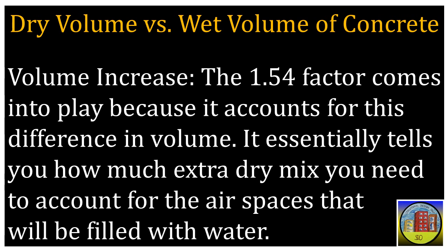Continuation of dry volume versus wet volume of concrete. Volume increase: the 1.54 factor comes into play because it accounts for this difference in volume. It essentially tells you how much extra dry mix you need to account for the air spaces that will be filled with water.